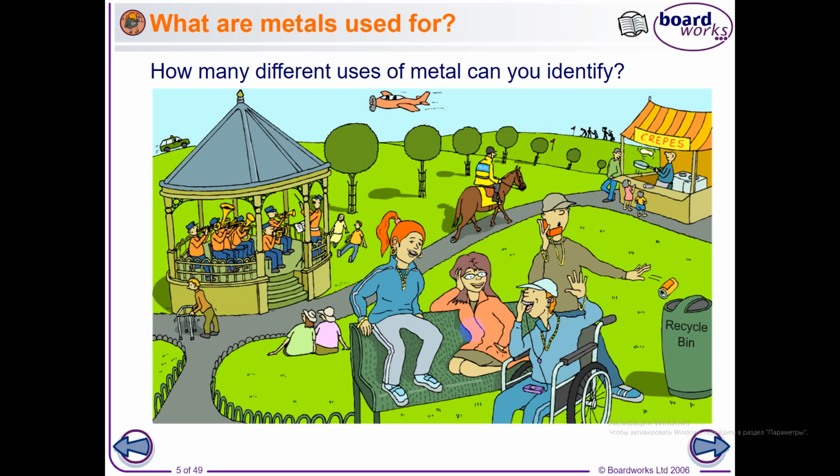There are three primary reasons why ferrous metals are so widely used. First, iron containing compounds exist in abundant quantities in the Earth's crust. Thus, iron is cheap in comparison to other metals. Second, ferrous alloys are very versatile in that they can be tailored to have a range of physical and mechanical properties.